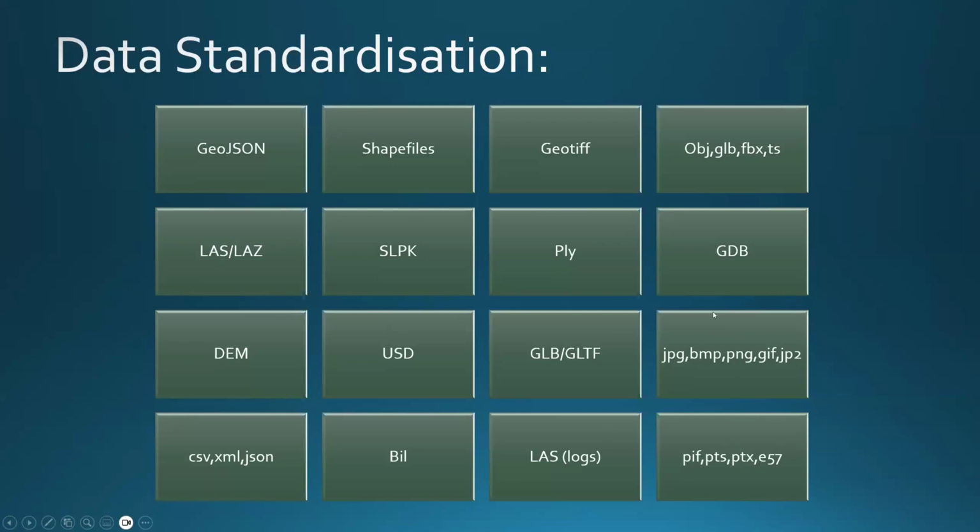But the data types we're looking at for the future, the ones I think you should look out for outcrop models, are OBJs and SLPKs. That's where we're going. Most of the shape models that I found are available in OBJ format, which is a good format for people to use. SLPK is very good if you're dealing with very large models and you want a tiled model system. It's called a scene layer package.